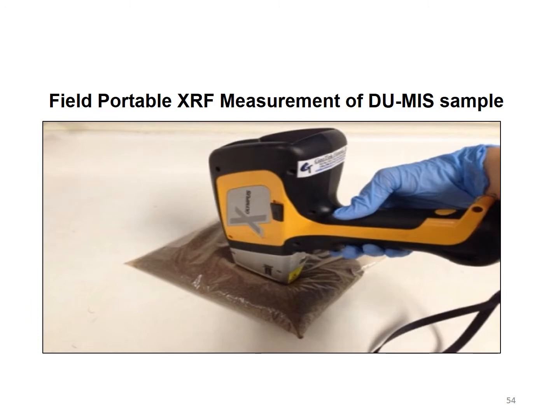like large surveys of looking for lead around water tanks, looking for lead, arsenic around building foundations where you may expect them, as an initial investigation just to see if there's any significant contamination there. Then if you get significant readings, you can come back and use those readings and that data to lay out decision units and collect those for more precise confirmation sampling.